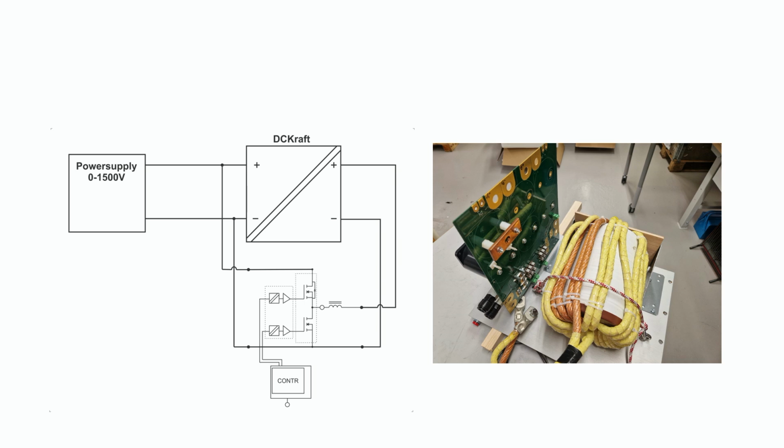So we have a lower voltage on this side than on this side. If we turn it the other way around with the inductance on this side instead and flip the low transistor, then we have a boost converter, so we have a higher voltage on the output side than on the input side. Still only supplying the losses to the system. So this works really well in the lab for testing.